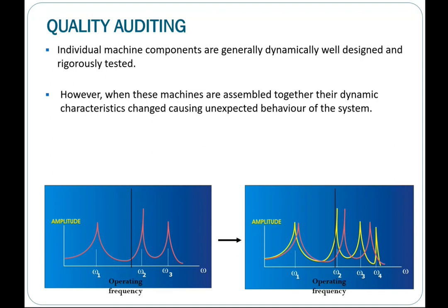Okay, it will change. The changes probably will fall into resonance issues. So without knowing the dynamic characteristics of the newly assembled machine, you do not know whether it will have any dynamic design issues or not.